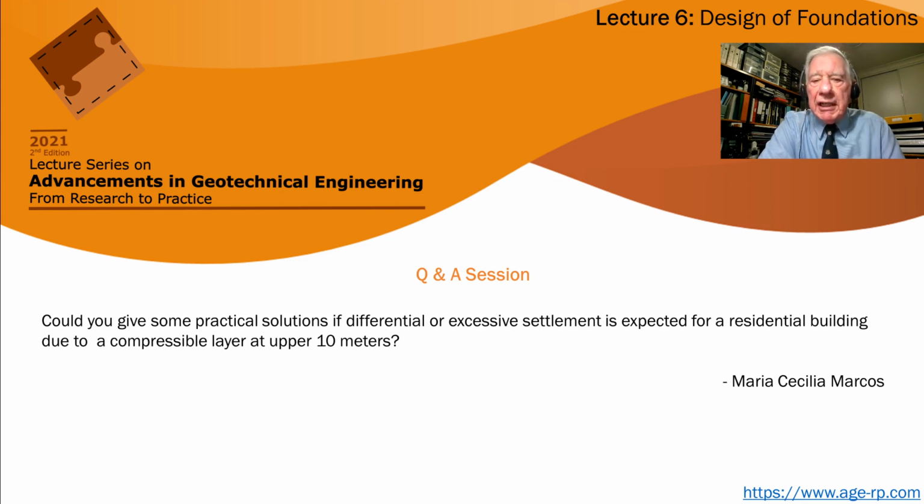I know this is often expensive, but again, you have to recognize that the level of risk associated with that solution is probably less than the level of risk associated with trying to use a shallow foundation and risking differential settlements.